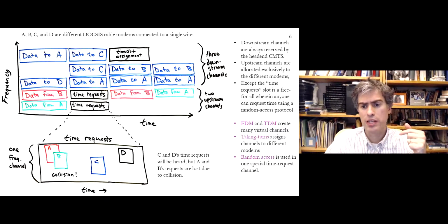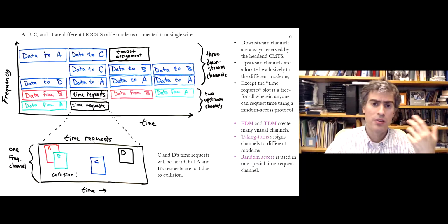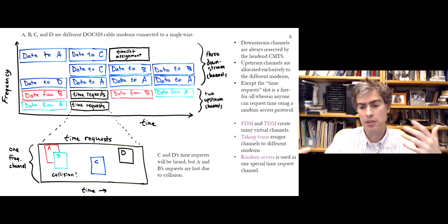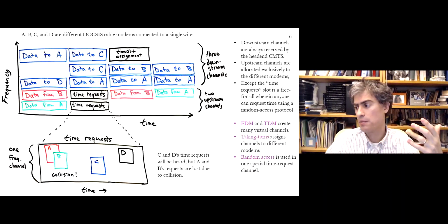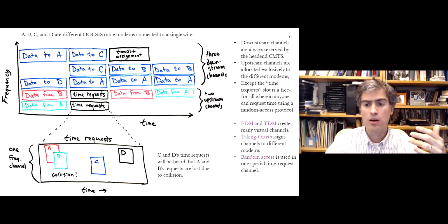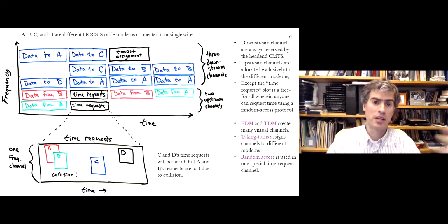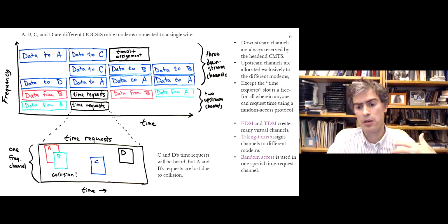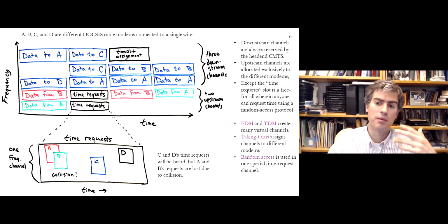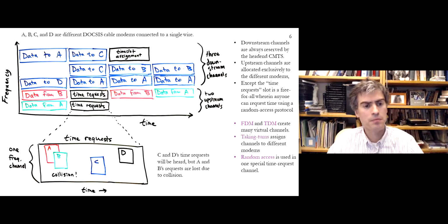And notice that there's more downstream channels than upstream channels. That's typical because, it depends on how many devices you're using, but typically home internet users are downloading data, not uploading data, and typically they're limited in the speed that they can upload compared to download. So they may only get 1/10 of the upload speed than download, and one of the reasons is that the way that's implemented is by providing more downstream channels than upstream channels. But that's generally what consumers want with home internet service.